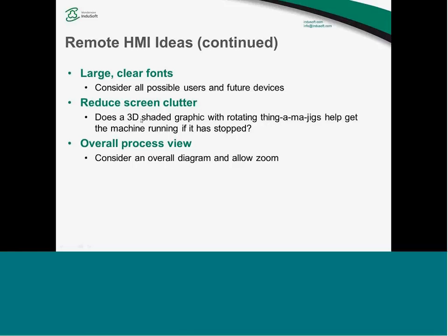Reduce screen clutter. Do those 3D animated shapes really help you get the machine running if it's stopped, or are they just in the way and maybe distracting you from where the real problem is? A big trend that we've seen recently is customers developing projects almost in grayscale, almost black and white, with color and animation used only when there's a problem or an issue, something that has to be noticed.